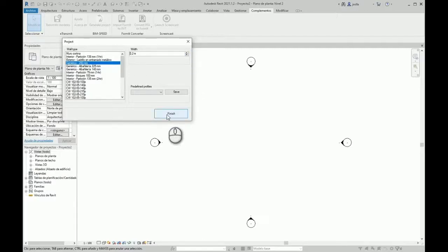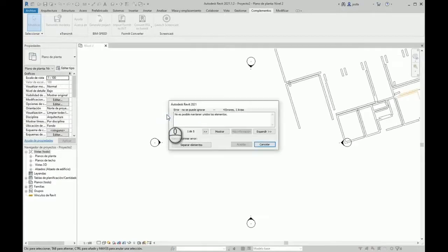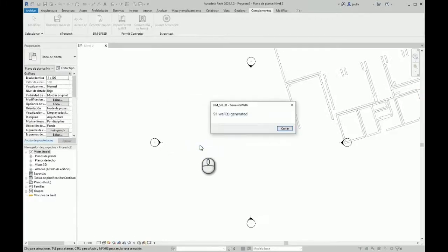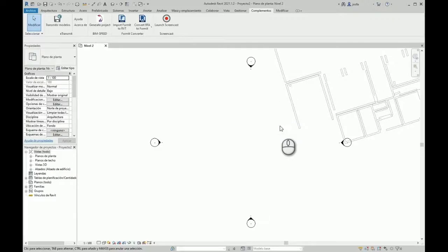We are going to select this option and use a value of 0.4 square meters for the minimum area. Configuration, load and save configuration profiles. The Parameterize button processes the cloud taking into account the selected values. Once the result is calculated, the next button can be pressed, displaying a new form where the project options can be selected.